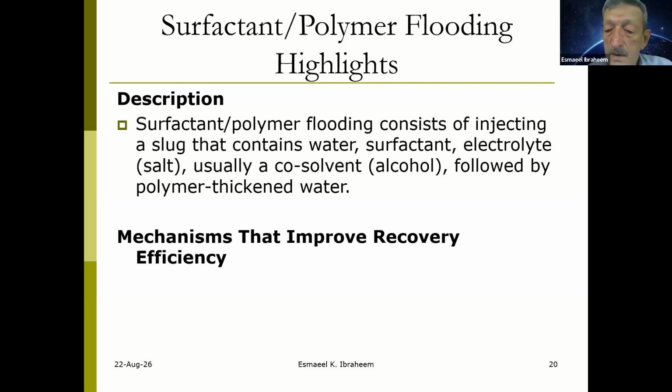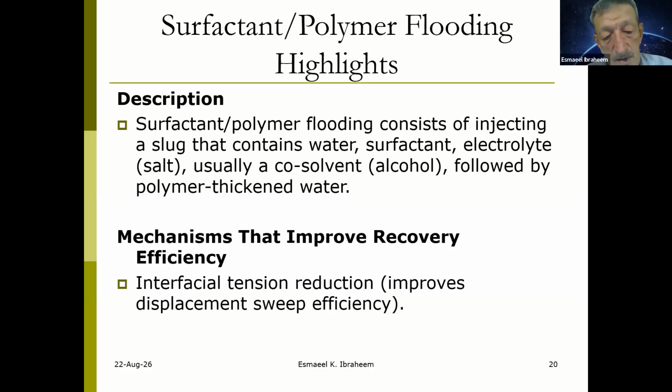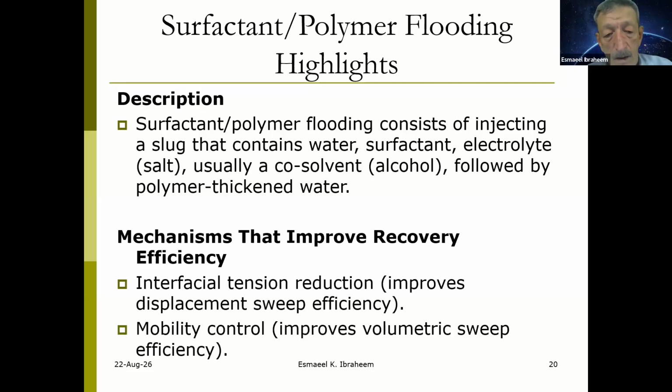So I said in the beginning, water injection and gas injection are the most dominant or most preferable use of enhanced oil recovery. The mechanism is that this mixture has interfacial tension reduction and improves displacement of sweep efficiency. Mobility control. You have to have control on the mobility of this slug, which improves the volumetric sweep efficiency.